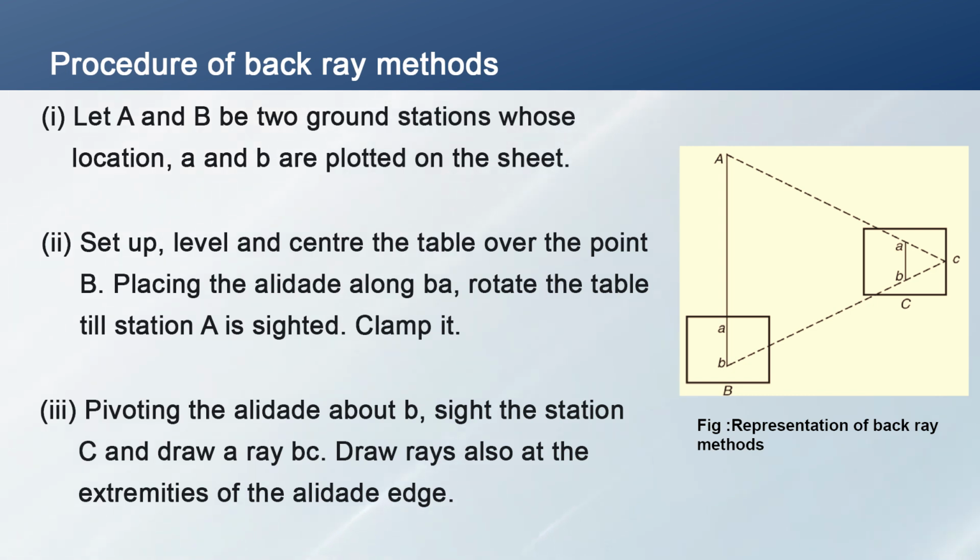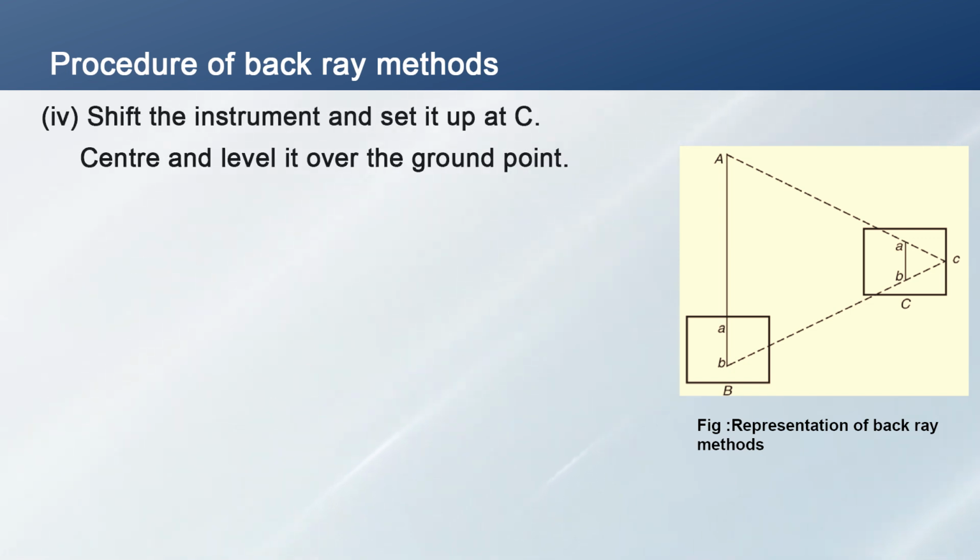Shift the instrument and set it up at point C. Center and level it over the ground point.